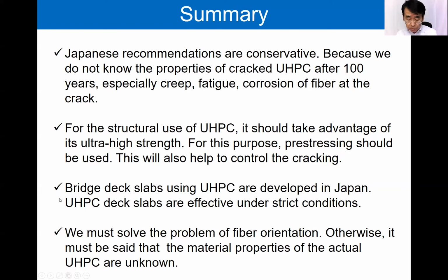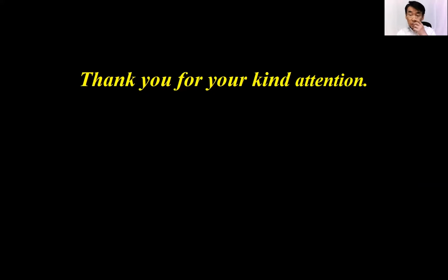Bridge deck slabs using UHPC are developed in Japan. UHPC deck slabs are effective under strict conditions. Finally, we must solve the problem of fiber orientation. Otherwise, it must be said that the material properties of actual UHPC are unknown in the actual structure. Thank you for your kind attention.